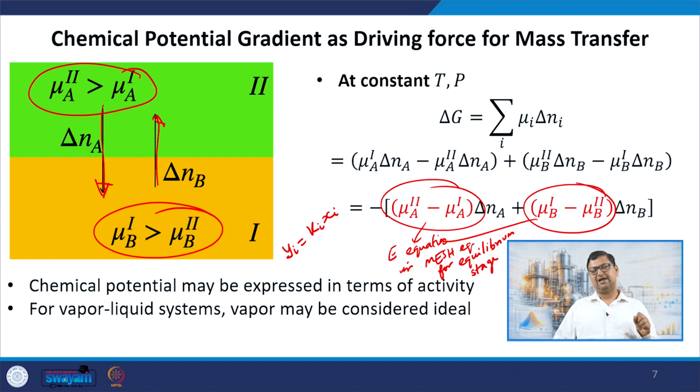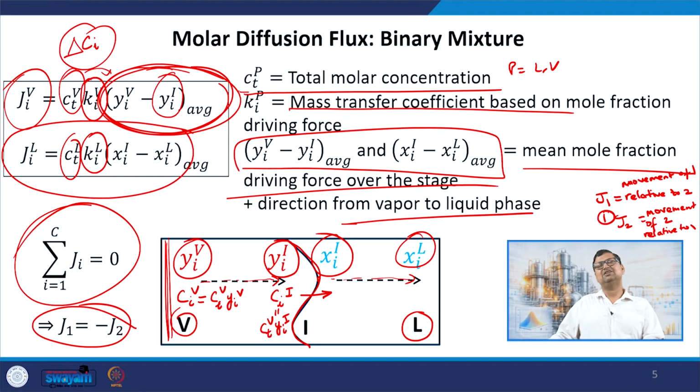But now, since we are looking at non-equilibrium effects, we are basically departing from that assumption of chemical potential equality. Now the chemical potential difference is actually giving me a mass transfer, and it is that mass transfer rate that should be considered as opposed to a concentration difference. That is the first thing that we have to keep in mind.